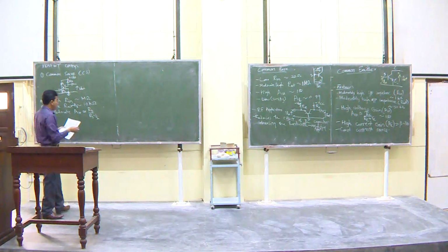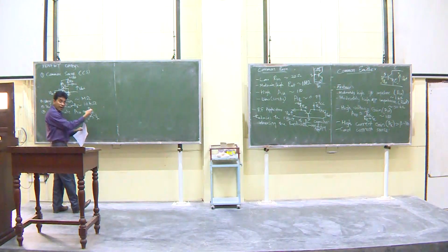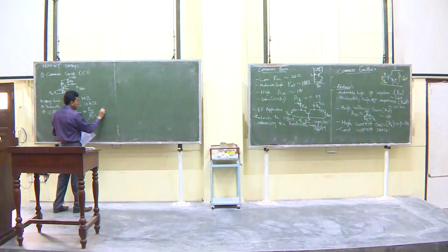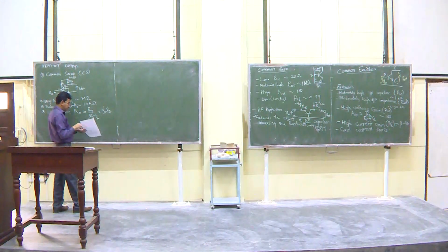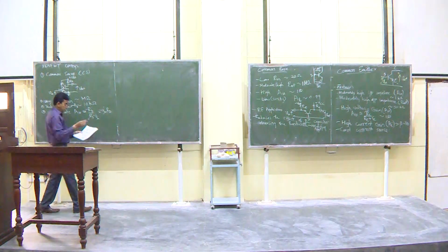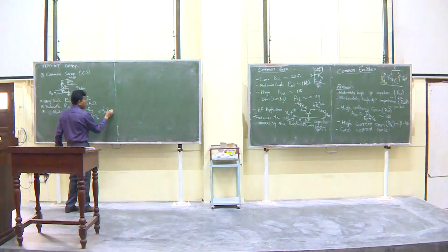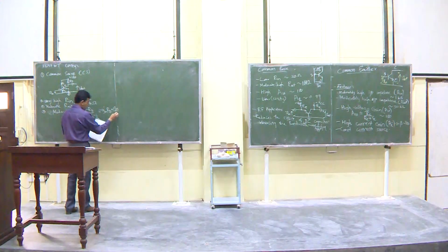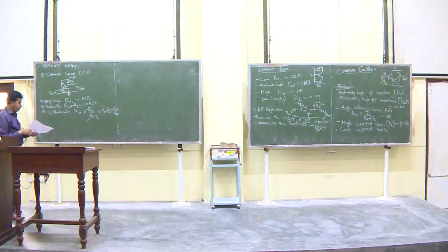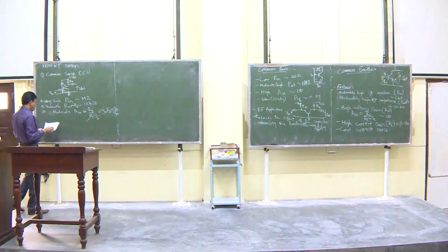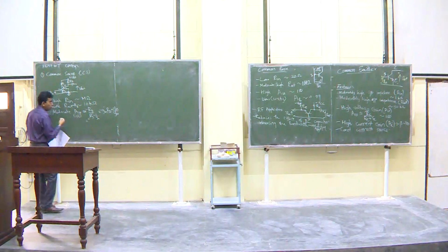So if this is 0, that is when you don't have a resistor in the emitter, this will be gm RD. But again, it's a negative quantity. VDS over VGS is the voltage gain. So this is the open circuit voltage gain.